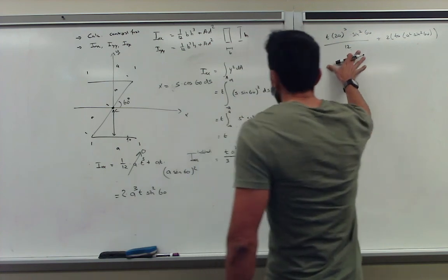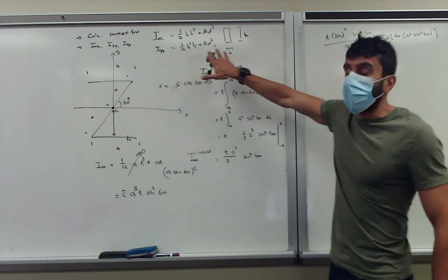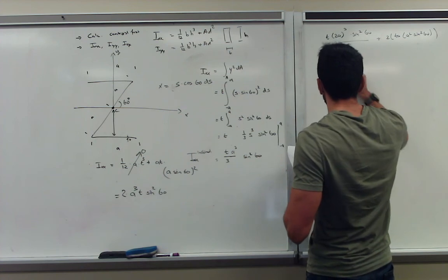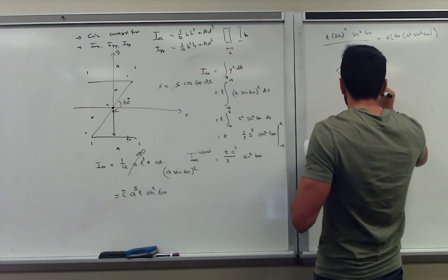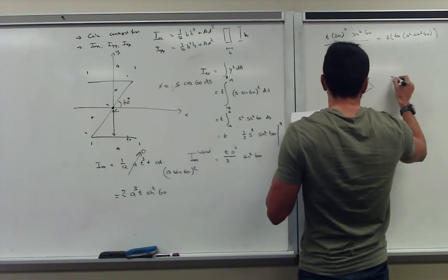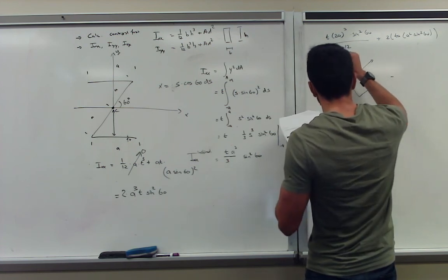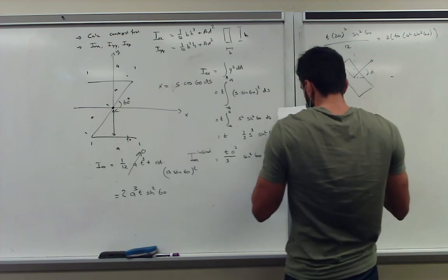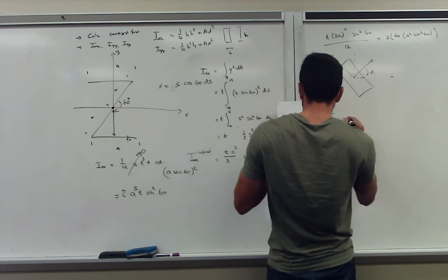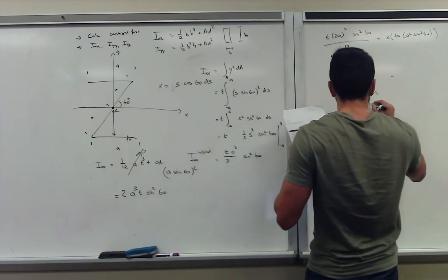So by inspection, this looks very similar to our standardized equation. And there's apparently a trick. It's on the formula sheet. I don't advise you to use it. It can sometimes be confusing. So it says if you have your rectangle and you have a given rotation axis of alpha, then the moment of inertia is defined as this part, by the way, this is D and this is B.